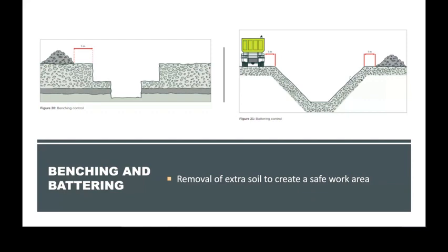Or just taking it right back to a 45-degree slope, which they call battering, where you're at such an angle that it can't collapse anymore. It's already at its stable level. The downside of those is that you've gone from a relatively narrow trench to a massive big pit almost. So that's why it's not usually used. There's a lot more work to dig all that out, and then a lot more work to put it back and bring it back to how it was beforehand.